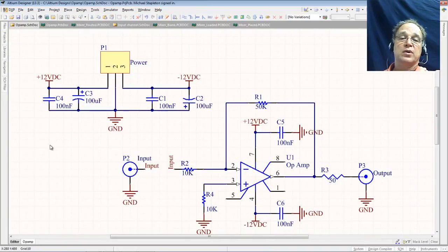So as I look back at our little op amp amplifier board we're building here, I have bypass caps here to protect myself from what's coming in from the external power supply. I don't know what it is, so I want to clean it up here. This will give me a surge current that's slower. This will take care of surges that are fast. And then I have bypass caps right next to the op amp to help take care of the problems of long traces moving all over the board from the power supply. I hope this helps you understand bypass caps, and remember, this is your board, your artwork, your design. You want everything to be nice and clean. Use bypass caps. Thanks.